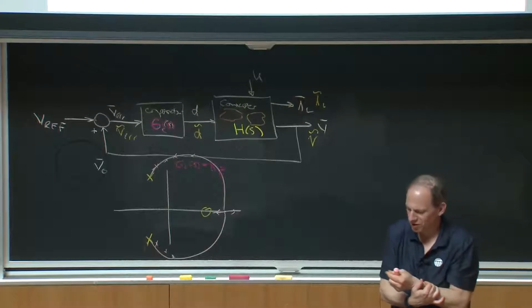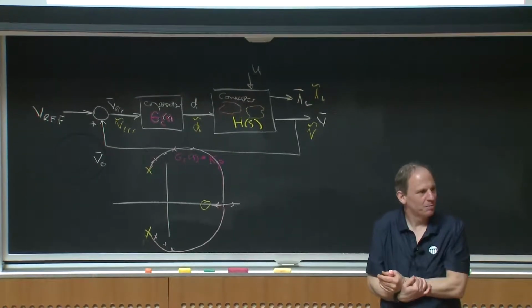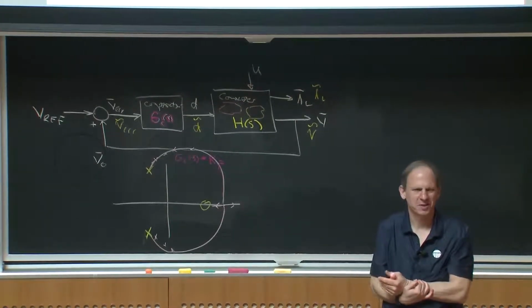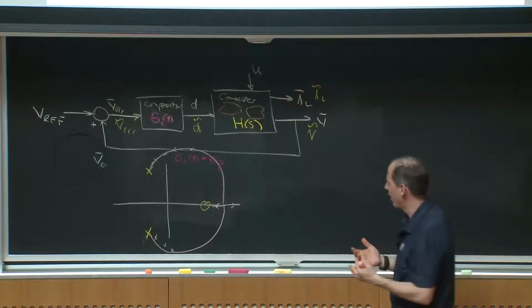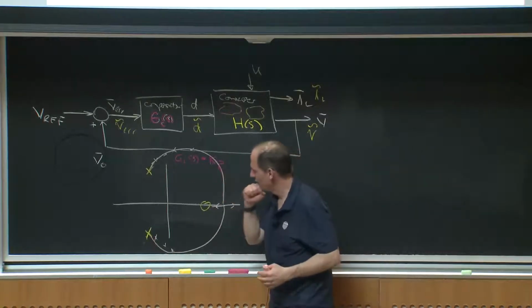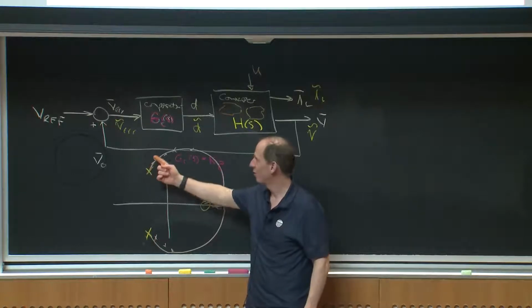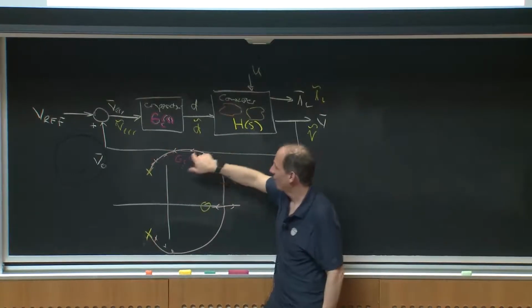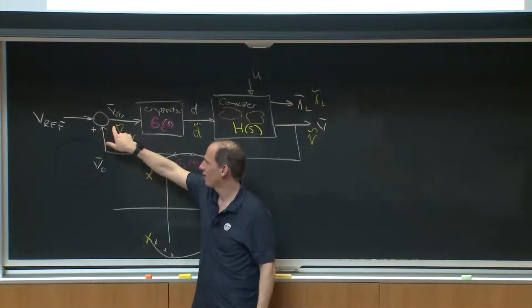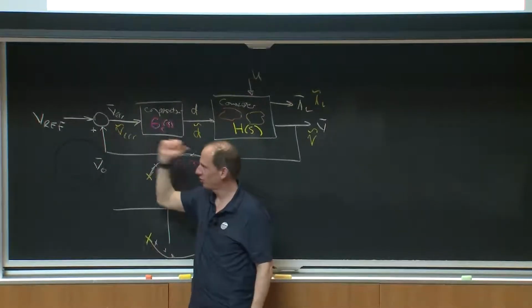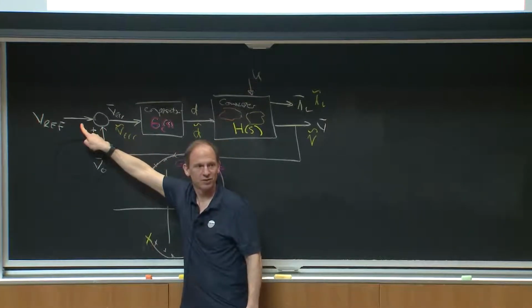Okay. So you wouldn't want to do a proportional compensator on this, because either it's going to have very bad stability, or if you limit your gain to a really low value, you're going to end up living with a pretty big error between the output voltage you're getting and your reference voltage. It's going to be a very droopy output.